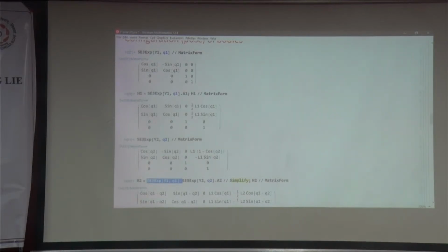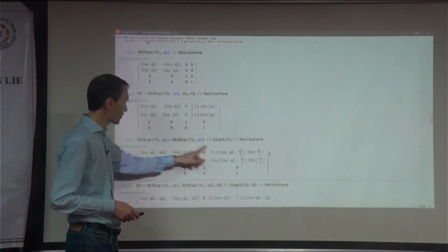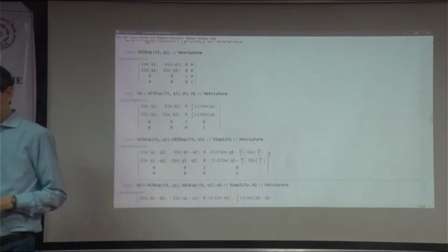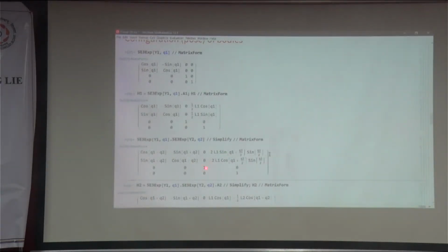So I'm actually interested in what happens due to the motion of... I'm not sure if it makes sense to look at this one. It just makes sense to look into this. Of course, the rotation is easy. So you get the combined rotation, right? What I'm looking at is what happens if you combine the motion of the second joint and the first joint. What happens to the orientation of the frame? You rotate about this and this together. So essentially, you get again a rotation about the z-axis. That's why we have this here, and the angle is the sum of the two angles.